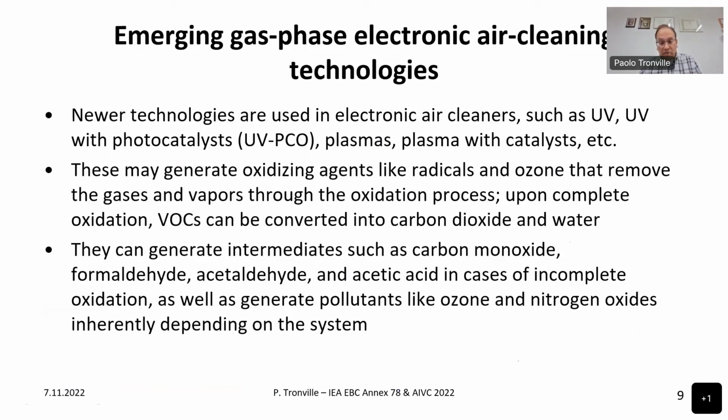So an ozone generator cannot be considered truly an air cleaner, simply because ozone is one of the contaminants of concern. And so even if they break down the contaminants, the volatile organic compounds, the technology must be checked in order to ensure that no harmful substance is released into the airstream and finally enters the occupied space.